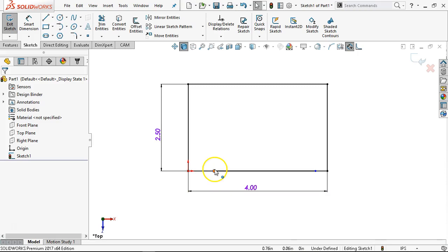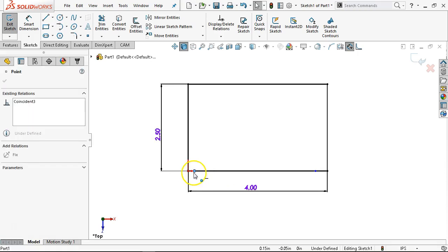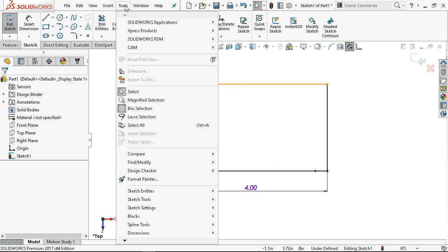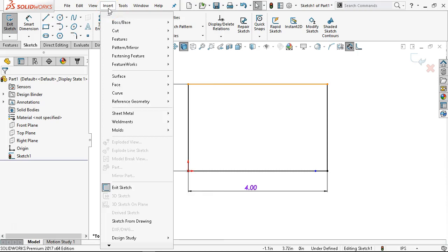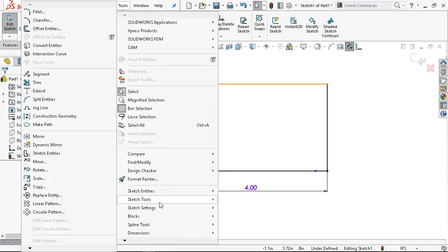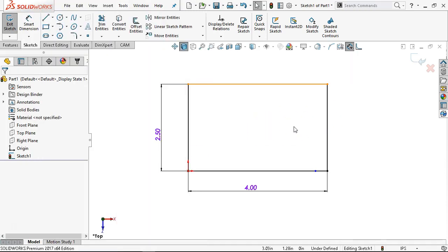And the trick is to identify the blue endpoints, or if they got related, then really the worst case scenario is that I'm going to have to delete objects one at a time until I find the one that's a duplicate entity. So as far as I know, even though I think I put in an enhancement request a while back, if not, it's time to put in another one. Under the tools and sketch tools was to delete duplicate entities. Most all CAD programs have something to remove something that is on top of something else, or at least be able to identify it.